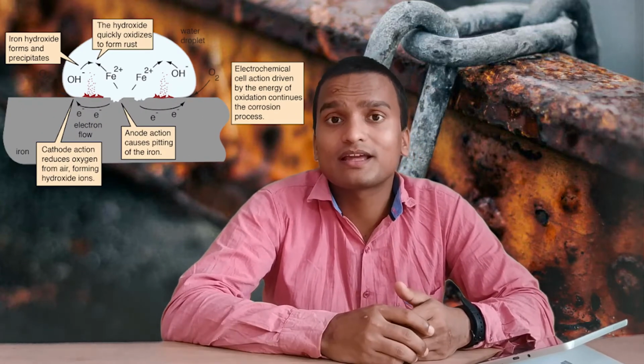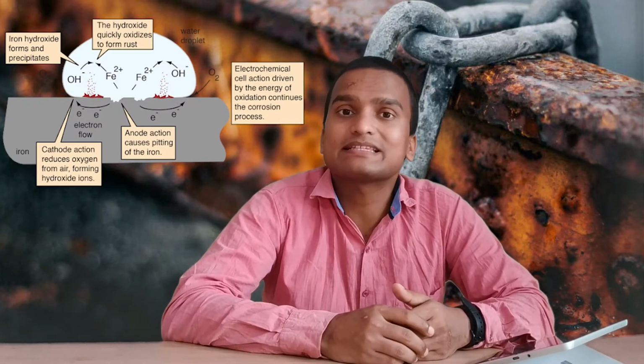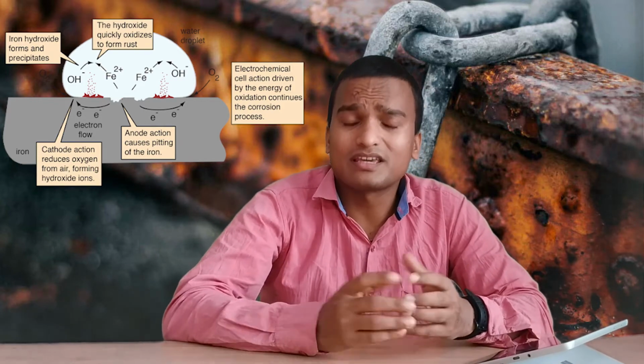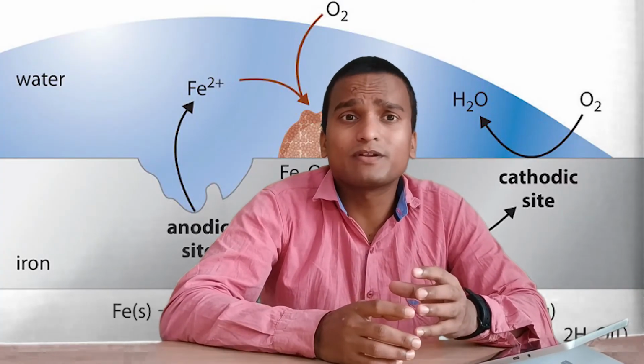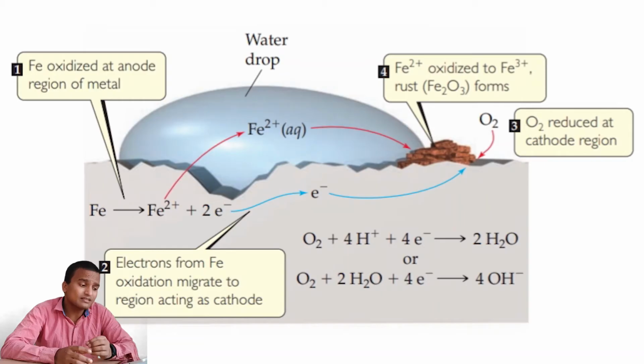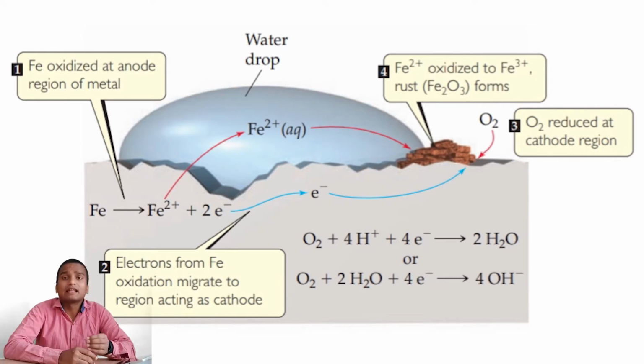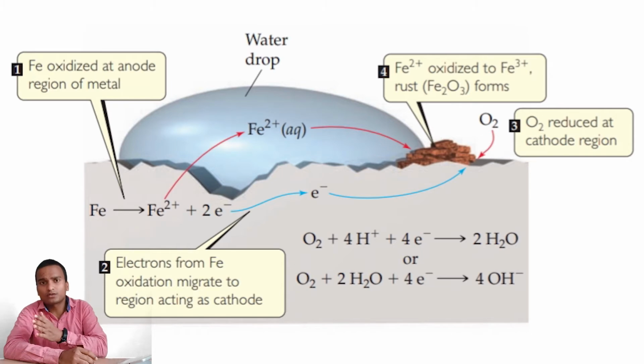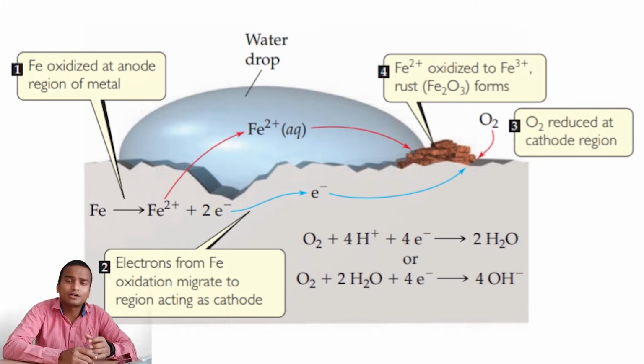See, corrosion is an electrochemical process which involves an anode and a cathode as well as an electrolyte. So in the case of steel, when the favorable condition for corrosion occurs, the ferrous ions go into solution from anodic areas and electrons are released from the anode and go to the cathode through the electrolyte, and there they mix with water and oxygen and form hydroxyl ions.